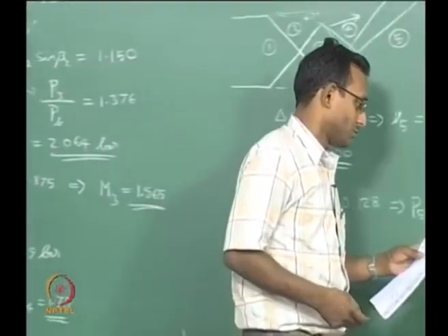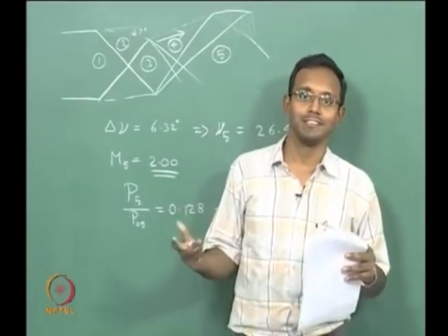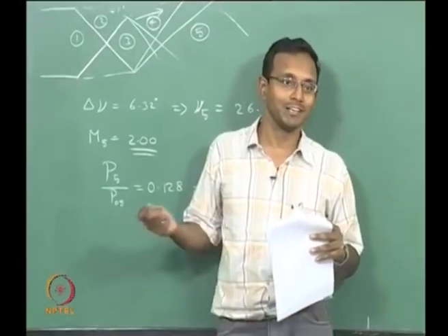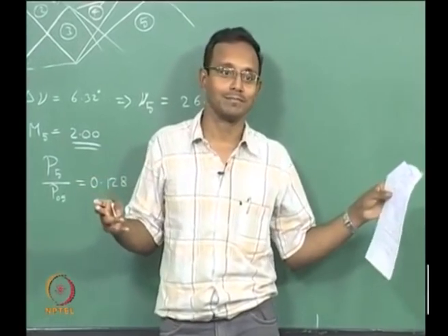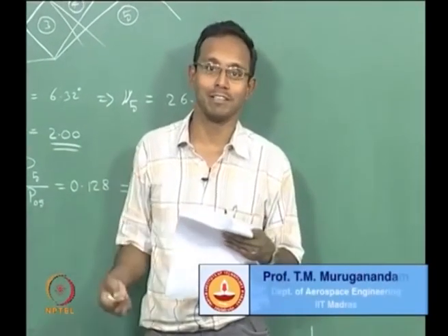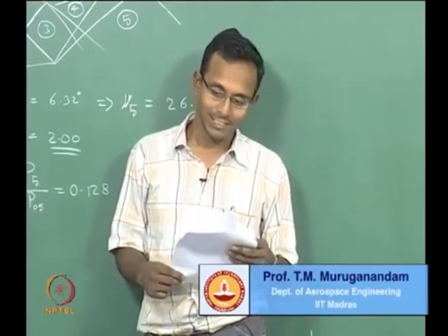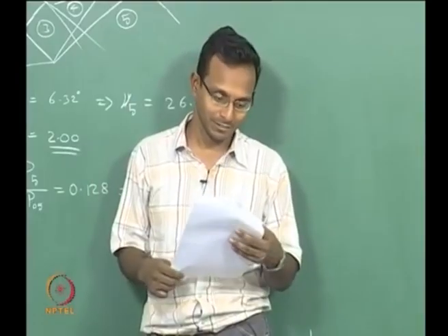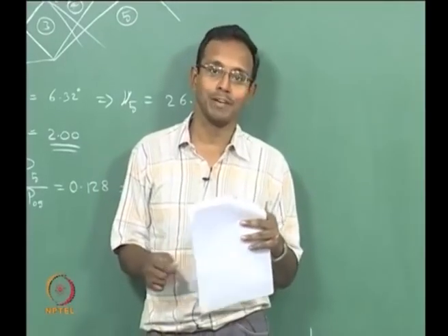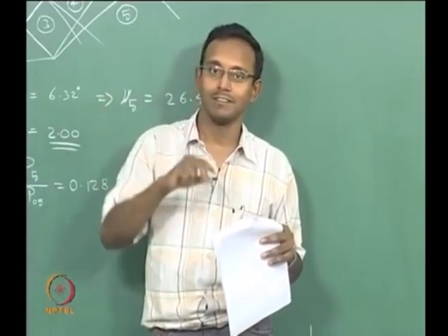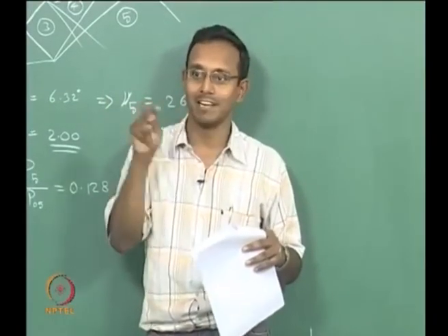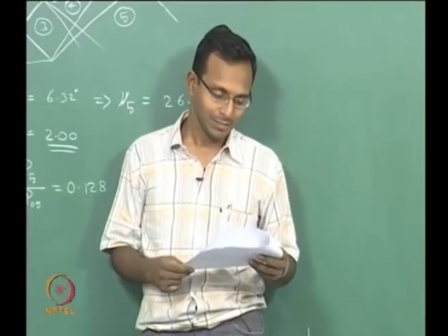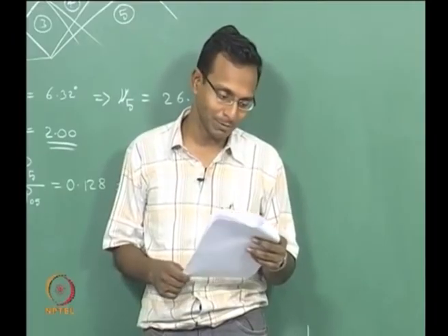Okay. So, when you are getting results like this, of course, you have to now think about whether your calculations are accurate enough. Now, you can say that your error band is really wide. Okay, you are getting results more than what is possible theoretically. So, that is not possible to have happen ever. There is some error somewhere in that. And it is most likely because I approximated beta from looking at a chart which does not have so much resolution. My grid levels are like 2 degrees, I am resolving it into 0.2 degrees, 0.5 degrees kind of numbers, not very good. That is where we had problems.